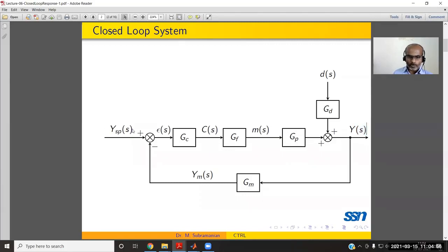So if you change the set point to 1, the output should also equal the value of 1. With P control, it is not reaching that final value of 1, the value of the set point. Instead, it is below the set point value. The difference is called offset. To eliminate offset, this integral action is good, but integral action leads to oscillations. So these are all the aspects we covered in the last classes.